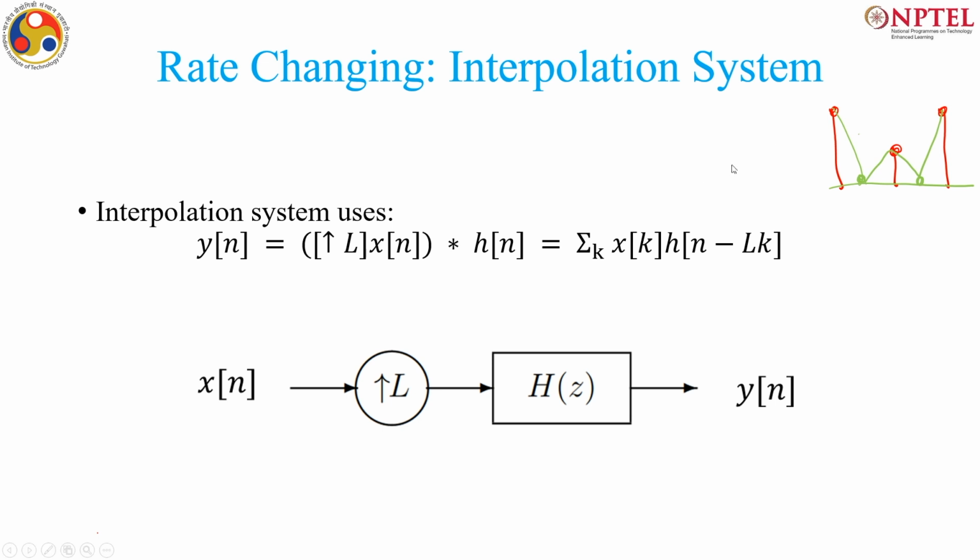Like if I do a linear interpolation, let me pick another color like blue, and if this value should be somewhere here and somewhere here, now this gives me a smoother estimate, and that is interpolation. So, how to do a smoother estimate? I can always do a low pass filtering, because in smoothing in time domain we studied what smoothing is: low pass filtering, because it will remove this sudden change to zeros to a smoother value. So, this can be done by using a low pass filter.